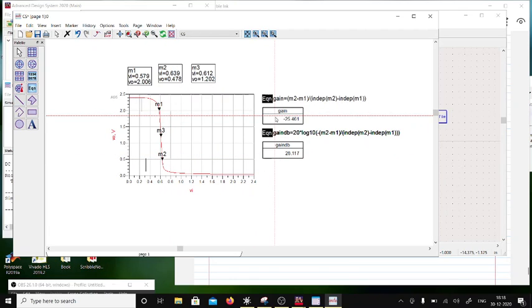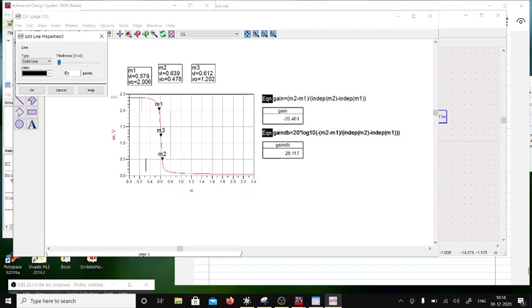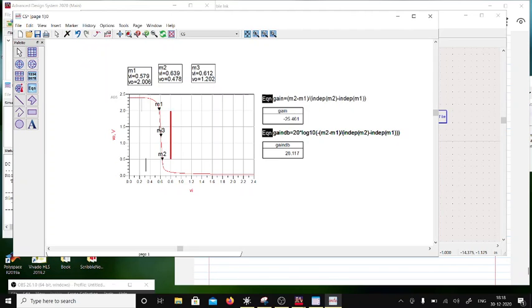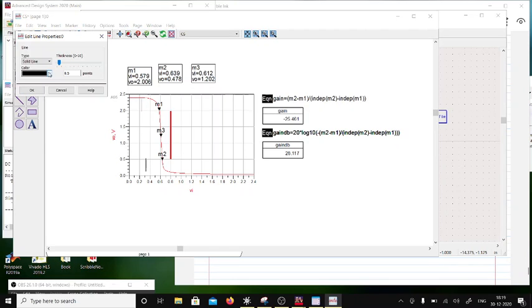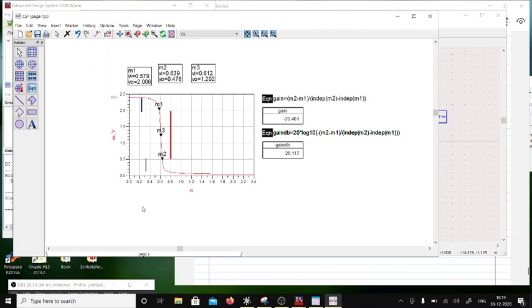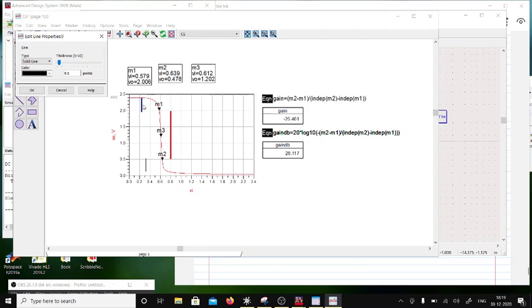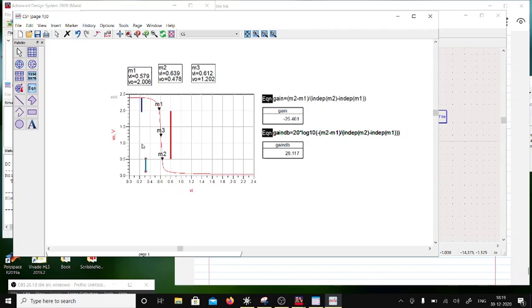Okay, so let me just tell you what's happening here. This is the net swing, and this one is V overdrive. So at the top you lost V overdrive because that voltage would cause the PMOS device to go into triode region. And this voltage will cause the NMOS device to go into the triode region. So you will lose all the gain because the RDS has gone.